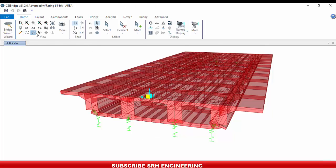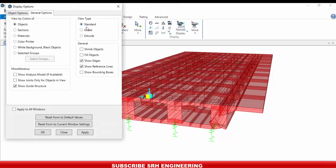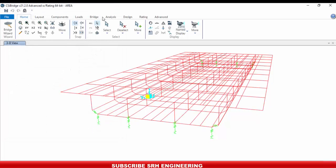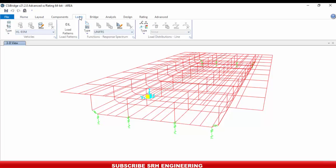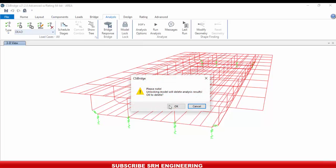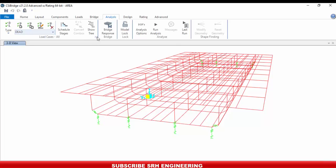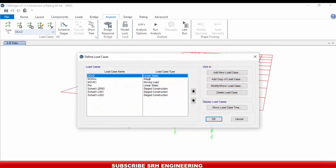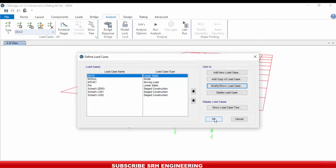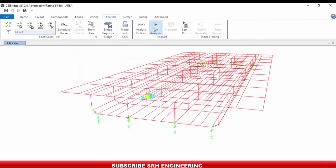To achieve that, we can introduce a reduction factor in my load case, which is somewhere in the analysis. So I have to unlock my model. I have to go here. In this dead load case, I can apply my reduction factor, which is 0.86. Then I can modify this part, and I can run it again.